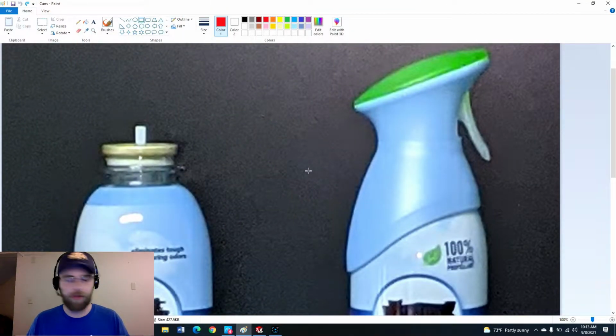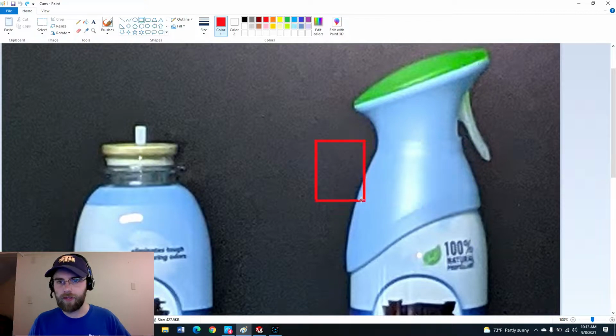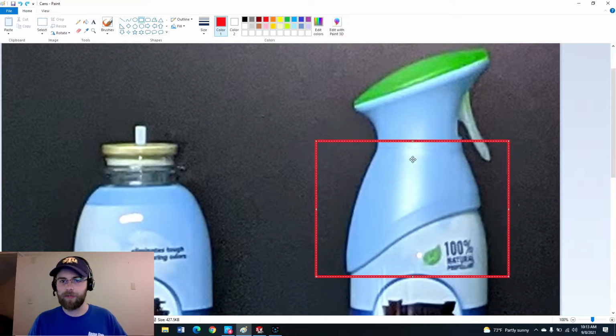So I want to start with a high-level plan of what we're going to do. The first thing I want to draw your attention to is we have a natural parting line right here, a flat, that separates this into some basic features. On this bottom portion, what I'm seeing is really just a revolve that's been trimmed away to get this nice little swoop along the bottom.